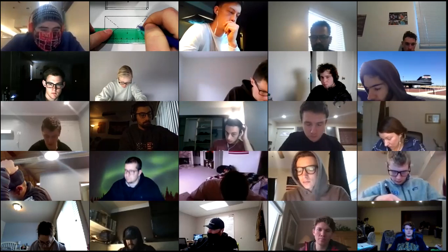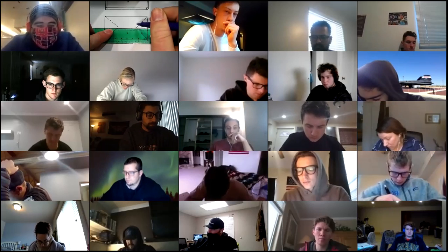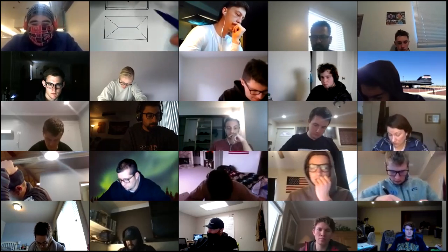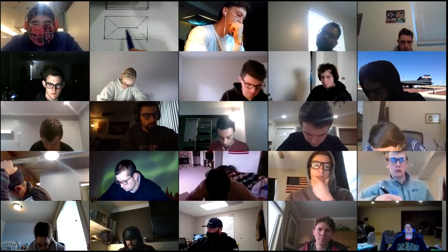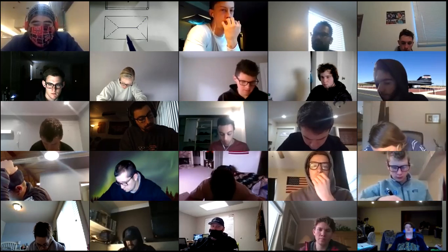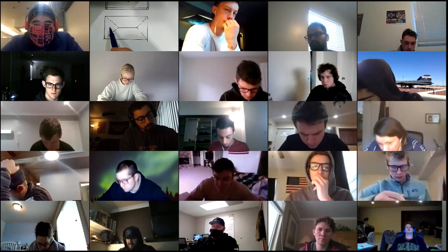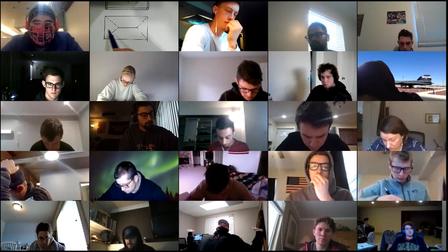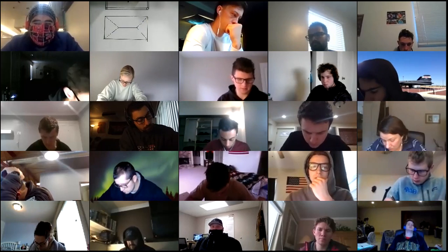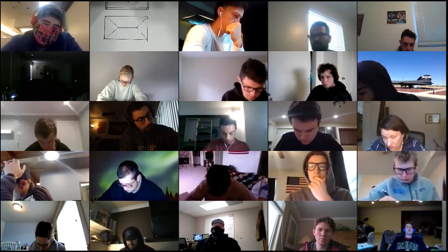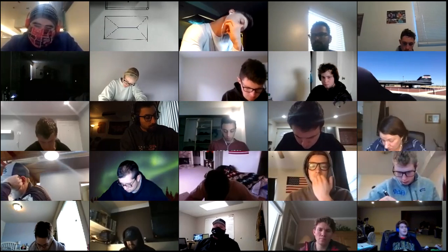And then between those corners, you draw another line. So what that looks like is one of these hip roofs, right? Here's the big flat section of the roof. There's the other section, and there's the end where it's also chamfered over. And that defines your tributary area to each of the edge beams.